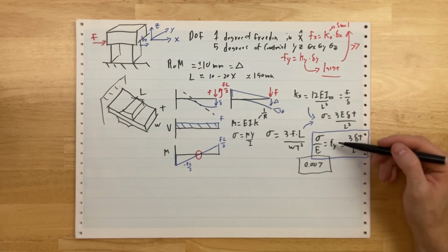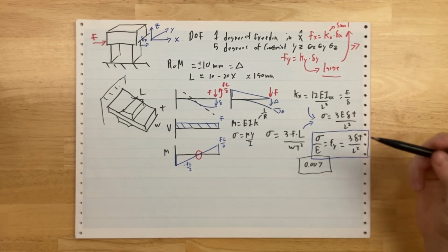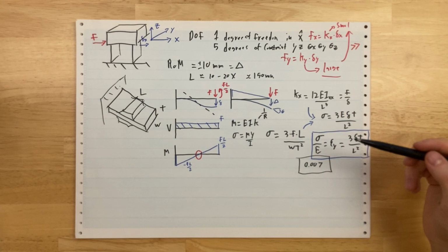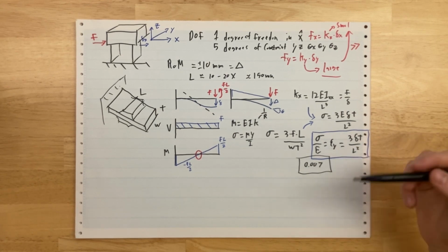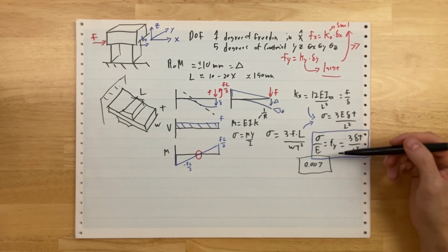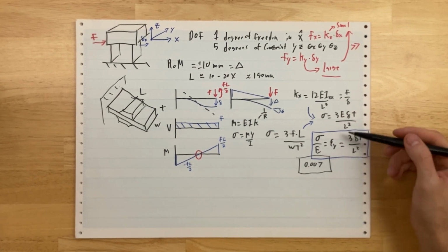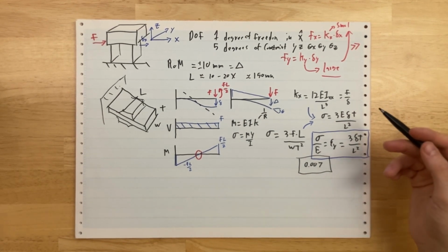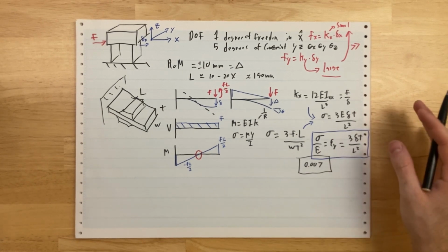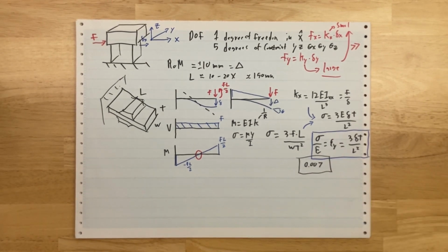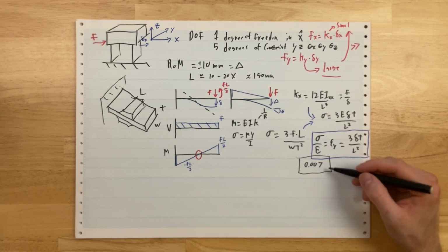Why would you want to use titanium or steel? Well, maybe you have an application where the absolute strength must be high, or the absolute stiffness must be high, or you're at high temperature, or you need much better fatigue properties, or weird corrosion concerns. Then you might use some of these other materials. But in general, if you just want a flexure to move a lot, 7075 T6 is a really good place to start.